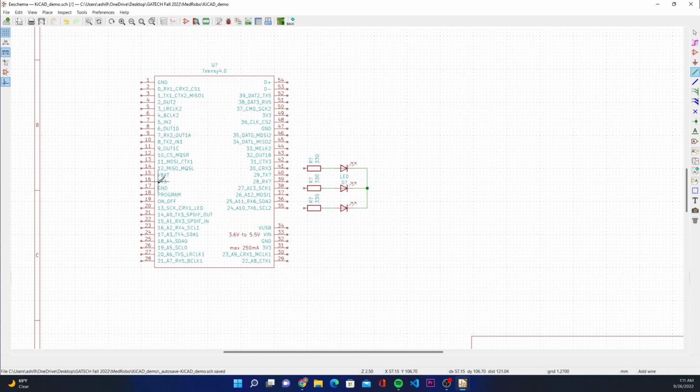And then we have the powers. So every now and then you have the 3.3 volts, the grounds, the VIN to power it, and stuff like that. So we want to connect this pin back to ground, right, to complete that circuit. So we can honestly pick any of these grounds, because internally inside the IC or inside the PCB, they should be all connected.